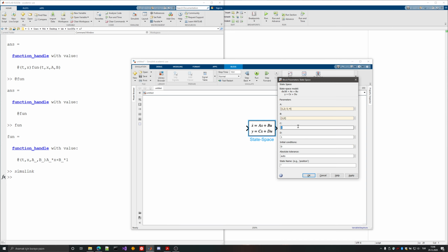but sometimes it's also a good idea to embed it directly. So keep in mind that we don't have the C and D matrices for a state space realization, but this doesn't mean that we don't have them. Basically, the question didn't define them, but we know what we want. We want the states, so this means that we can define our own C and D matrices if they're not given.